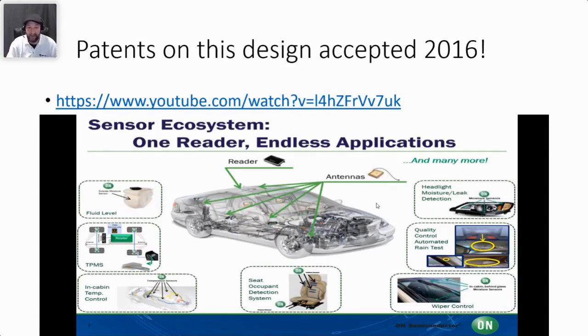But what's interesting about these new ODS systems that we'll probably end up seeing soon is that they're wireless. Seat weight sensors are completely wireless. Everything that they're doing here, some are Bluetooth. Some of them are actually running their own private Wi-Fi network on the Wi-Fis that are already installed on the cars, but it's new and it's going to change. So yes, these are the older systems that I touched on. The 2018, even still kind of an older system now.